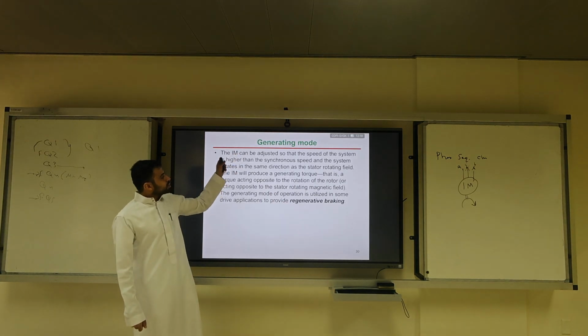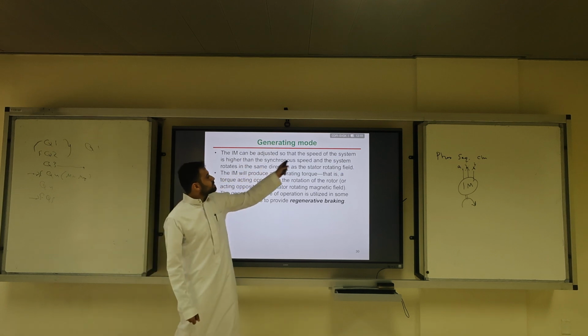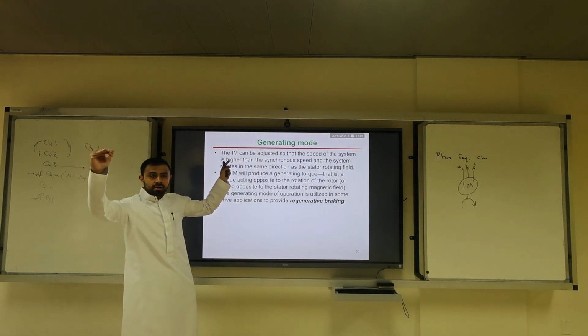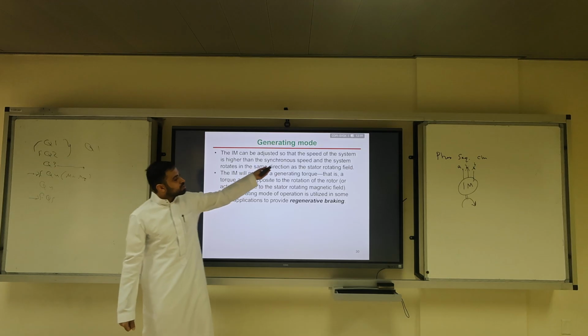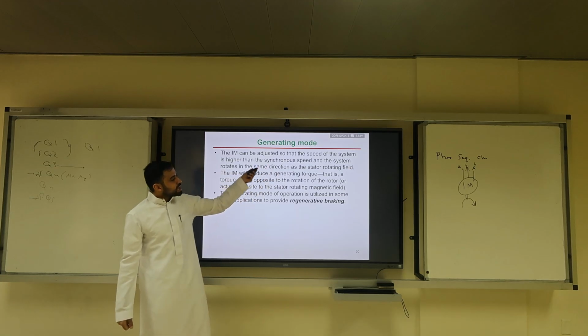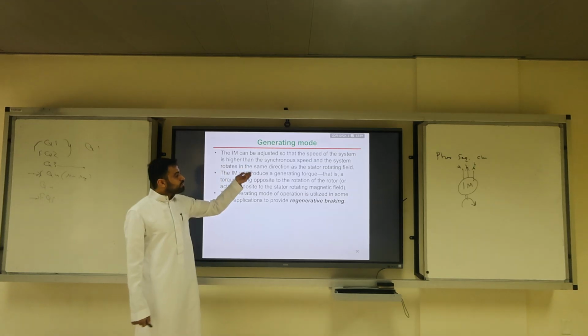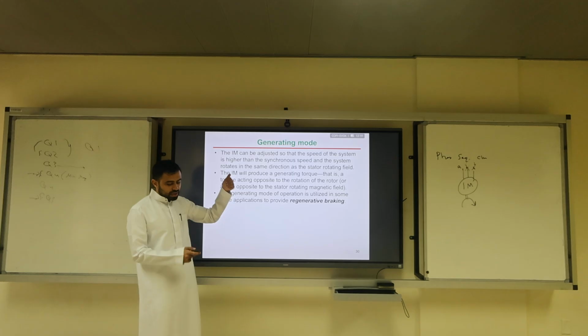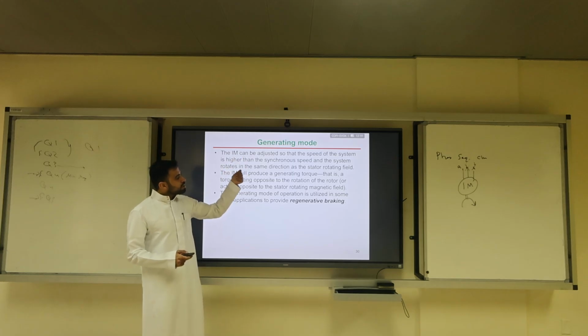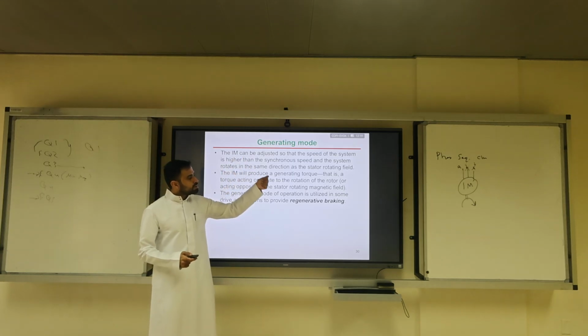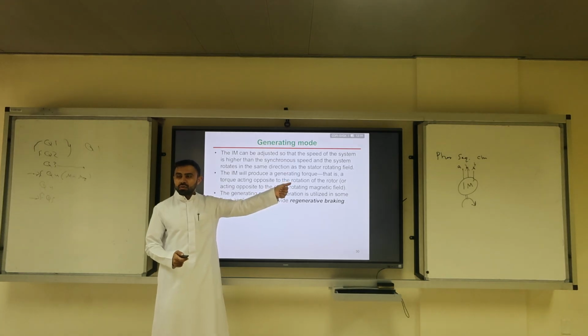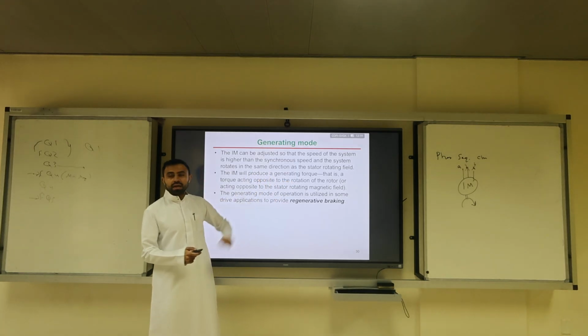The generating mode: the induction machine can be adjusted so that the speed of the system is higher, by an external factor, than the synchronous speed, and the system rotates in the same direction. Still we are in the same direction. This is one of my favorite questions I'm going to have in the test. For the generating mode, we are in the same direction of the RMF.